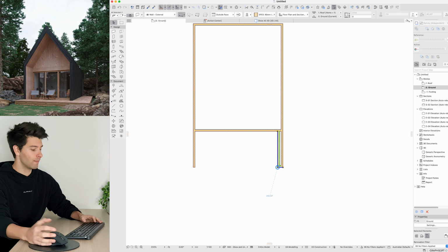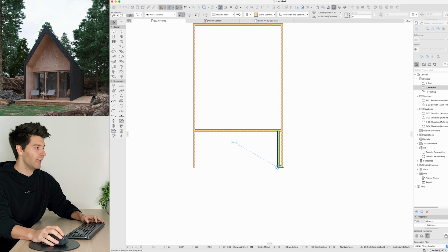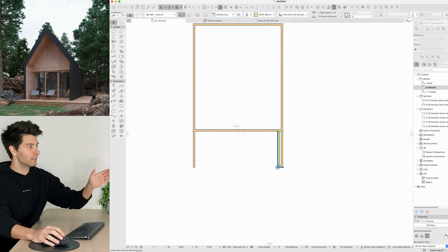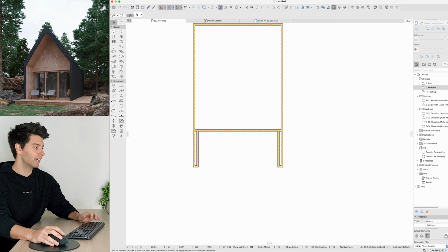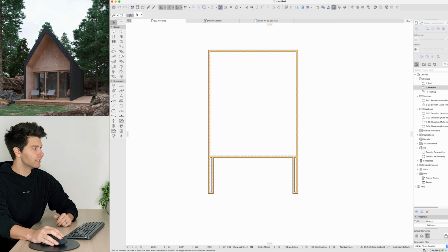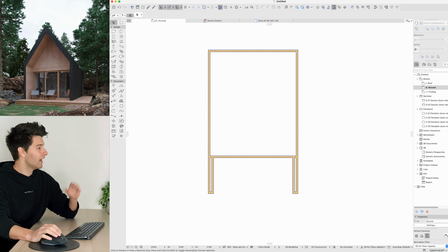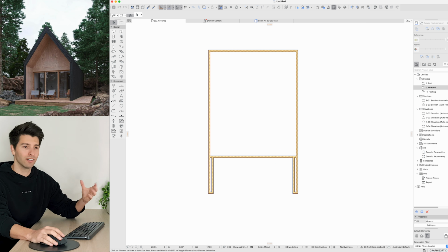Now, so I don't have to repeat that exact same process, what I'm gonna do is click on that wall frame I've just created, Command M for mirror, find the center of our wall and our house, tap Option or Alt to be able to actually duplicate it, hold Shift and click again. Now, all of a sudden, within a couple of minutes, we have the outside perimeter of our entire design.